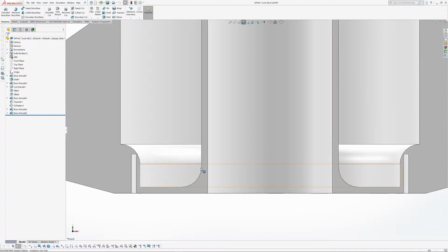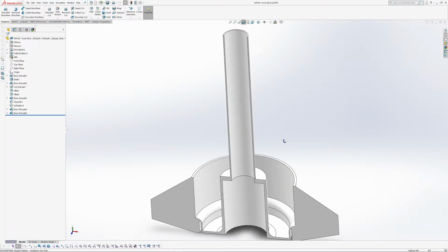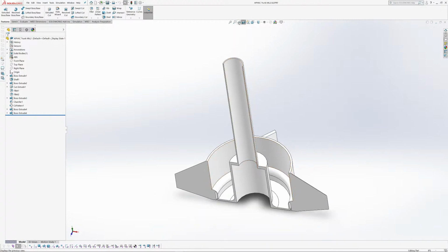By adding this fillet, it distributes that force, and instead of just having a shear force, it's a lot more distributed and stronger along that line. That's why we needed to add it, because we saw that that was probably the reason why that failed, and we wanted to prevent that in the future.